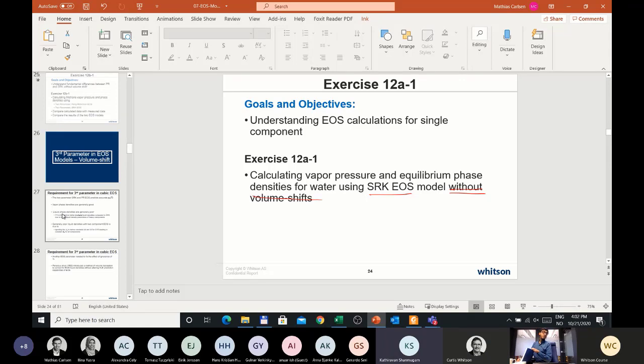There is another question. Actually, apart from these SRK and Peng-Robinson models, nowadays I think there is one more thing called the Cubic Plus Association (CPA), which is being introduced by software like Multiflash. I think KBC has made CPA the default model. Could you also elaborate on the application and usage of the CPA? Is it being used in a reservoir simulator? Yeah, the Multiflash, but that's not a reservoir simulator. That's more for process simulation.